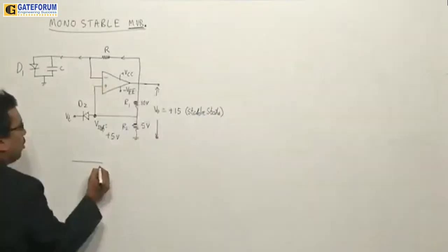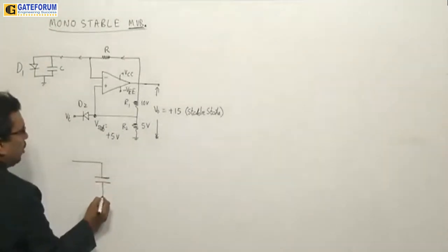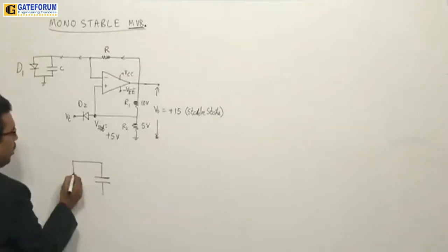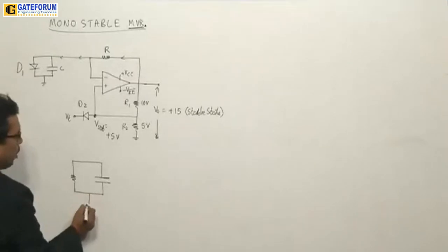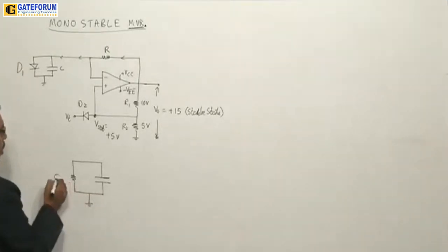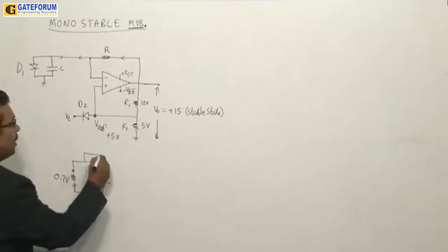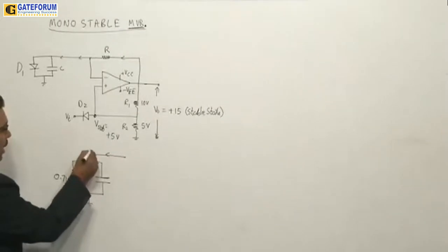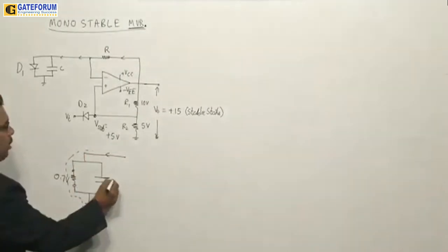When the current comes through the diode, it is very risky whenever you have a diode in shunt with any other device, because at any moment if the diode gets forward biased, the shunt element will not have any more voltage. Its voltage will be fixed. A practical diode under forward bias acts as a closed circuit, which offers very low resistance. Because of that, the entire current will go through this diode and reach the ground.